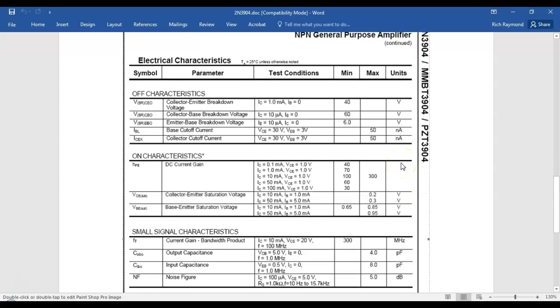Are we okay? Minimum 30. Right. That's what we're going to use for a saturated switch. So a saturated switch gives us the current gain between the base current and the collector current. So let's say I use a beta of 100. That means sometimes this thing would saturate and sometimes it won't. What we're trying to do is make sure that this thing saturates, whether it's wintertime, summertime, anytime. So if I get a beta of 100 but I designed for a beta of 30, we're fine, right? You understand? This is like we talked about in class.